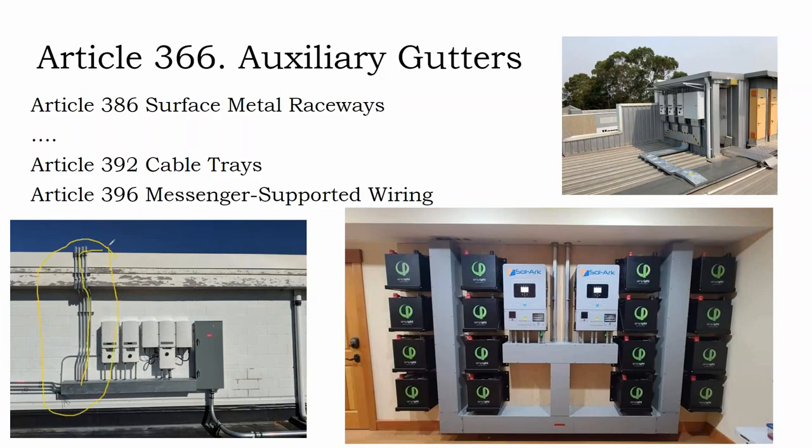Because by the time you evaluate all of that work, you're spending as much on labor instead of getting a higher quality finish. So what the gutters do is allow you to simplify all of this. We have 8 different circuits or 8 different conduits that might contain 2 or 3 circuits in them landing inside here. Each of these circuits needs to get divided between multiple inverters, and then also come out and go into a broader box before we get back to our main point of interconnection.